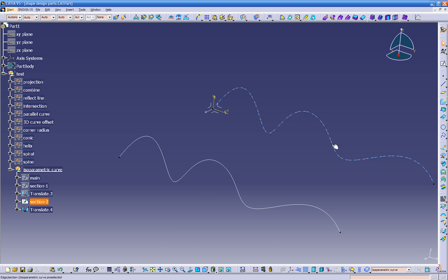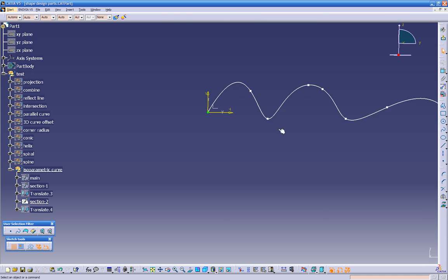If I'm gonna edit this shape right here, which is this sketch, automatically it's gonna update my translate sketch because they link together. So see, I'm gonna hide this right now, and basically this is what I'm gonna edit. But the moment I edit this, that's gonna update my translation. So I'm gonna just double click.